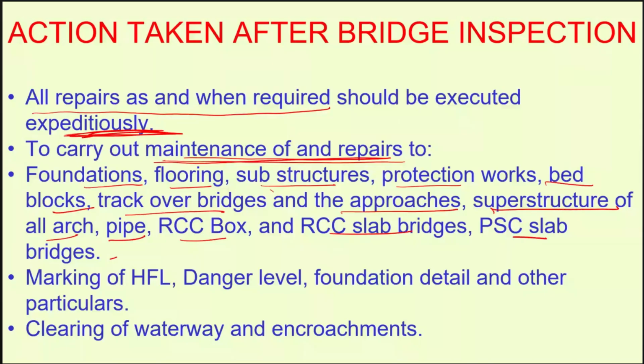In the bridge, we have to mark the HFL level and danger level, so as to ensure that a natural calamity due to flood, etc., never overwhelms our situation and makes the structure fail. Foundation details and other particulars should be marked so that we know what the foundation is, at what depth it has been founded, and what the type of soil is. Clearing the waterway and encroachments: many times, if there has not been rain or flood for a long time, many of those areas which are prone to flood will be encroached.